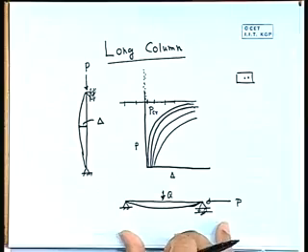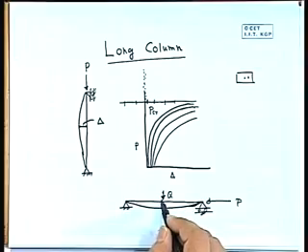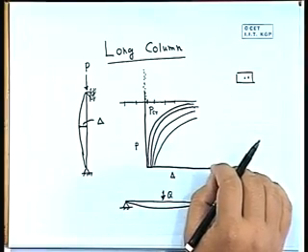Now here, the structural element whatever I have drawn, this member is called a beam column, because here there is a load. If P is not there, it is a beam. If Q is not there and P is there, it is called a column. When P and Q both are there, we say it is a beam column problem. Now in the beam column problem, the deflection estimation is absolutely nonlinear. So it is not linearly dependent on Q and P.